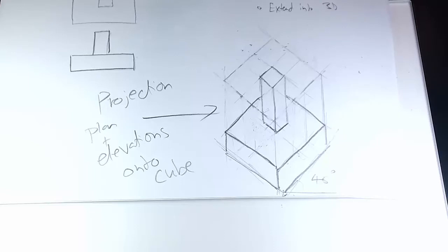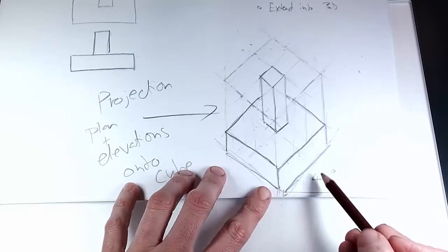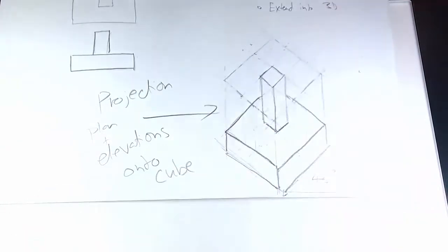Okay, so I asked you for, I'm going to rush a little bit because I want to get onto the isometric projection. Axonometric, we've got a 45 degree angle because we're using the true plan area to create the illusion of 3D. In isometric sketching, we actually use an angle of 30 degrees to the horizontal to create our construction lines in the horizontal plane.